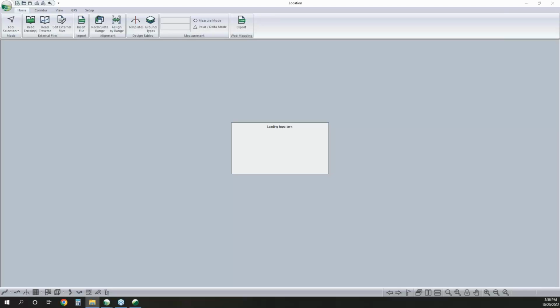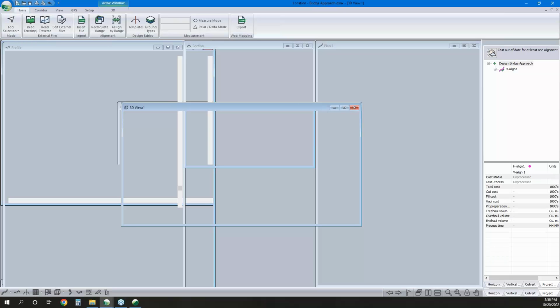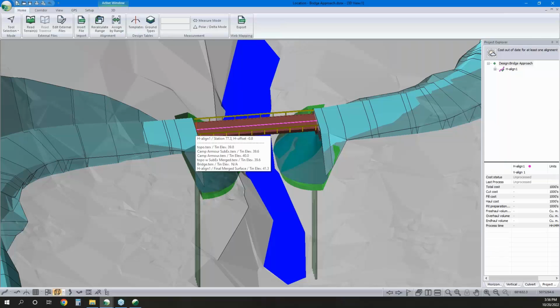Crossing's a crossing anyway. You can design your bridge sites in RoadEng. With that, there's a couple things to consider. One is you're probably going to want to model the abutments as something other than an alignment. So with our roads and culverts, it makes sense. We've got a center line and we can attach a cross-section geometry to them and model things quite well.